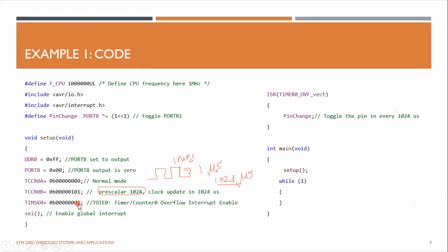Okay, so that is set. Also, if you look at the previous external interrupt lecture, you will see that we have to enable the global interrupts if you want to enable any kind of interrupts. When you use this function, global interrupts are enabled, which means you are telling the CPU to enable all the interrupts, and then only you can enable this interrupt.